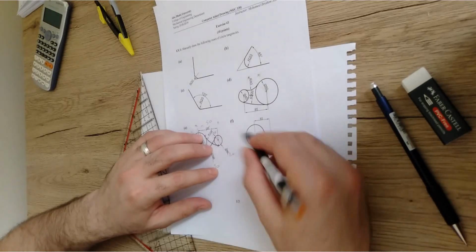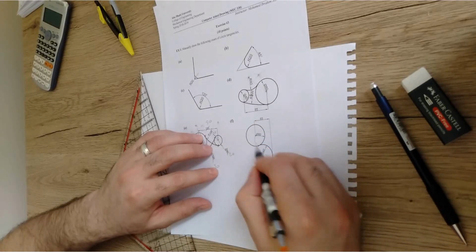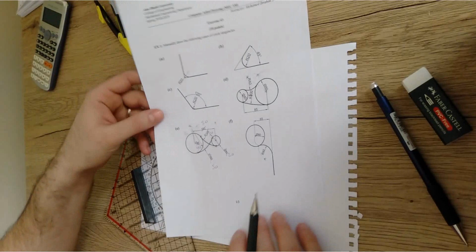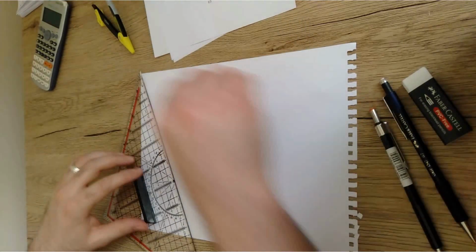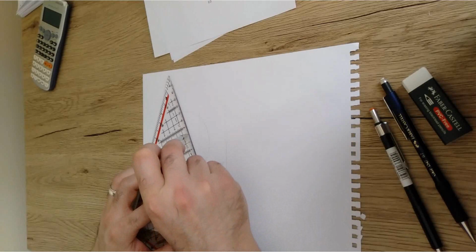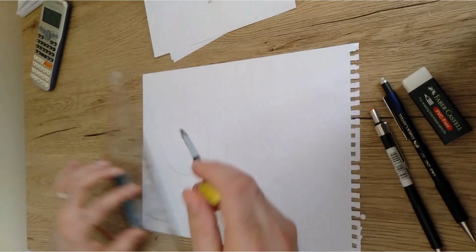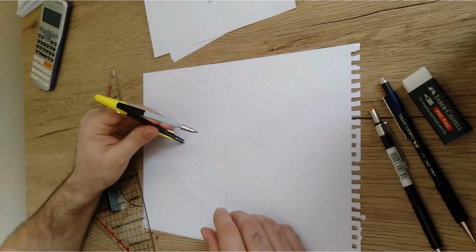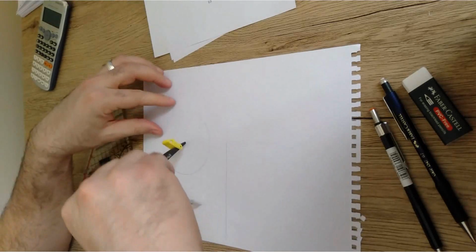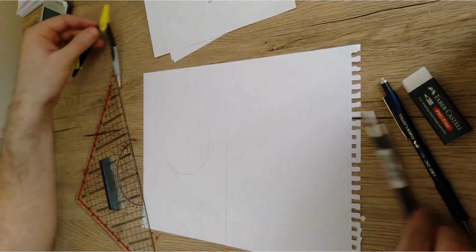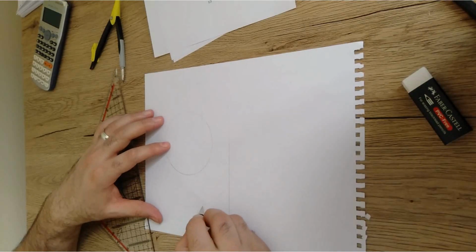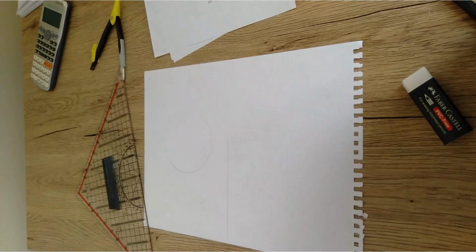It means that we have to sum. We're gonna sum the 40 plus the 40. This first 40 is the radius of the big circle plus the 40, which is the radius of the curve itself. It means that we have to open the compass by 80, and then we're gonna end up with another curve that defines the second locus of the curve. From this center, we're gonna draw a curve. This is gonna give us the second locus. The intersection of these two loci at this point is gonna give us the center point.